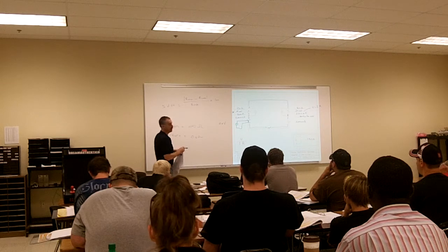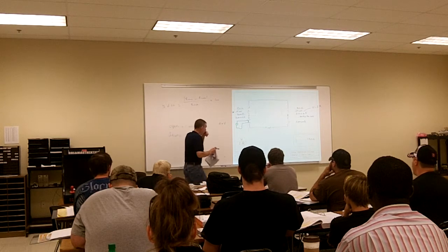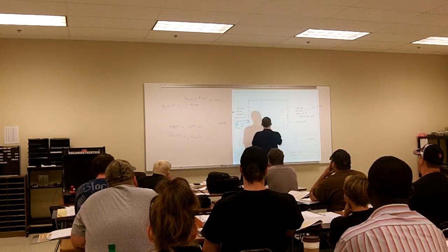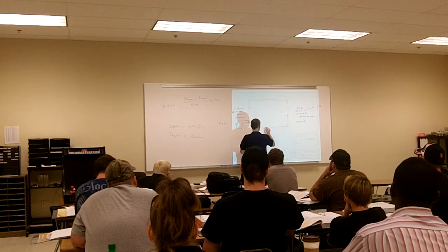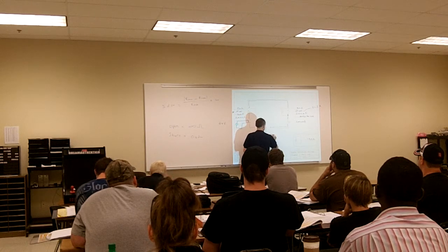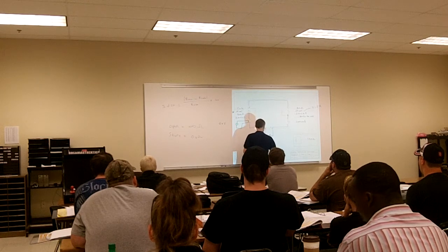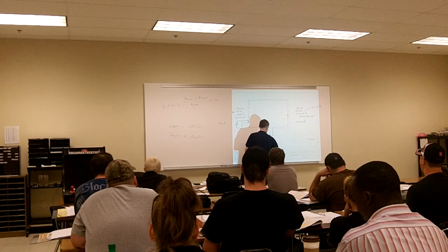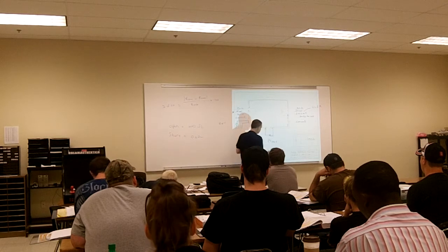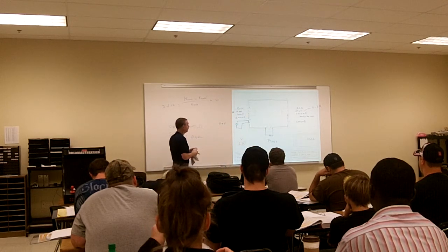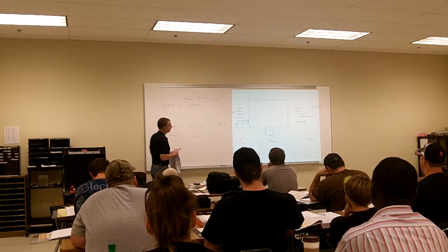Switch. The switch. So now I check my switch. So now I go and measure across my switch, and I hook up my voltmeter to it. And I end up measuring 24 volts. Is my switch open or closed?